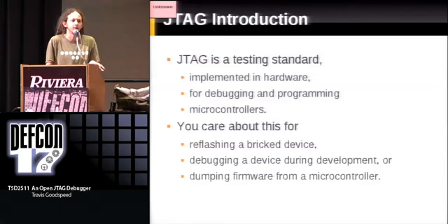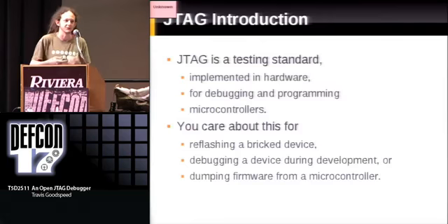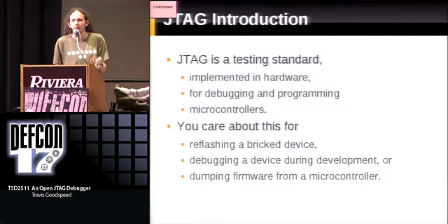If you're trying to fuzz, say, a wireless sensor, you can run it at 1/1000th of real time, and the device will still work. The radio doesn't care how slowly the microcontroller speaks to it. The application itself will chug along. So you can fuzz these devices and actually watch the stack grow just as you would in a simulator, but on actual hardware without having to re-implement all of the hardware in simulation.